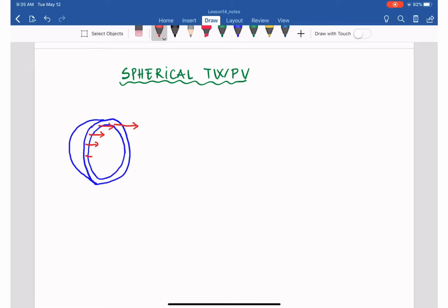stress on the material that makes up the tank, as we did in the cylindrical tank previously. We call that sigma. In the spherical tank we call it just sigma, the hoop stress and longitudinal stress are the same. This one we simply put as sigma because the sphere is symmetrical in any direction.